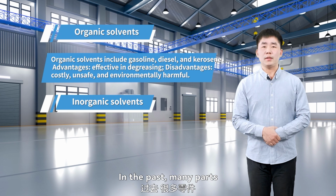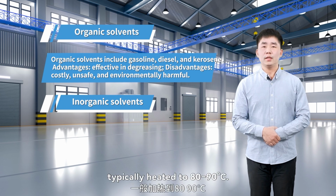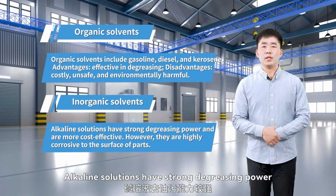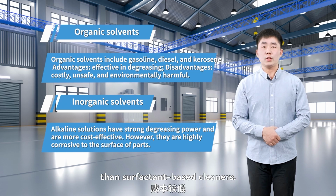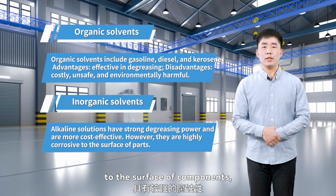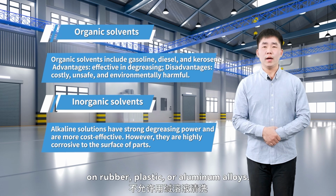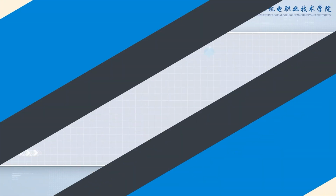In the past, many parts were cleaned with alkaline solutions, typically heated to 80 to 90 degrees Celsius. Alkaline solutions have strong degreasing power and are more cost-effective than surfactant-based cleaners. However, they are highly corrosive to the surface of components, especially for non-metallic and non-ferrous materials. So they should not be used on rubber, plastic, or aluminum alloys. Additionally, alkaline solutions can irritate the skin.